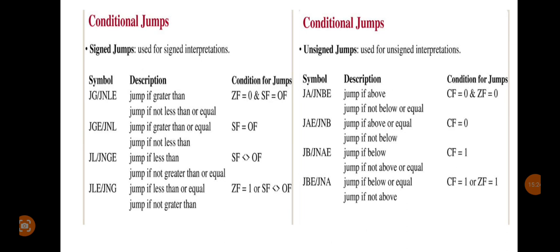Similarly, unsigned jump is used for unsigned interpretation. That is, when you are dealing with unsigned numbers, only the carry flag and zero flag will be used. For signed interpretation, you should use the overflow flag and the sign flag.